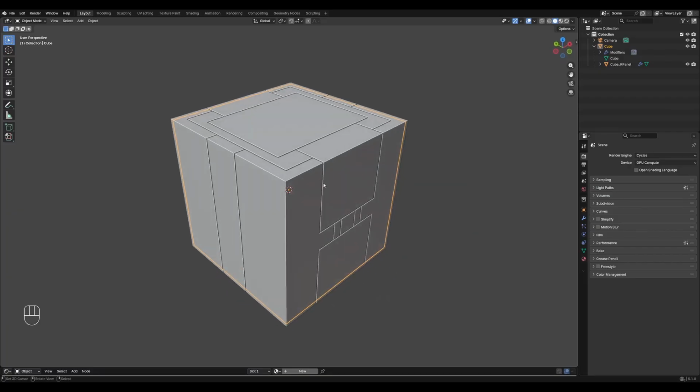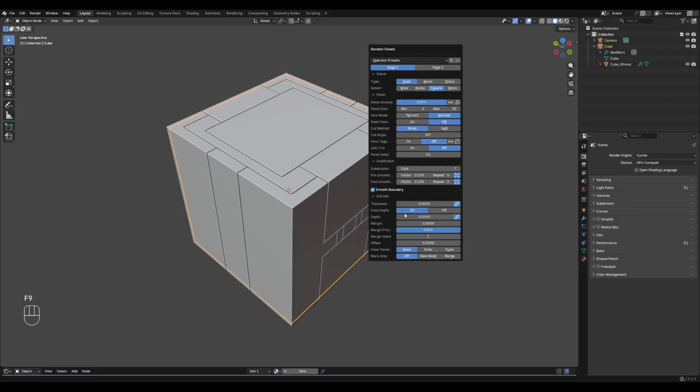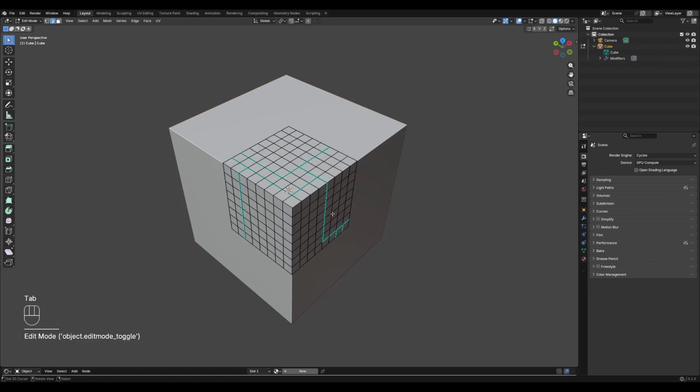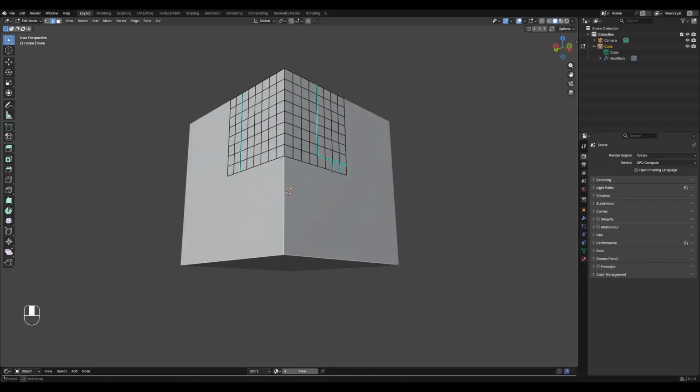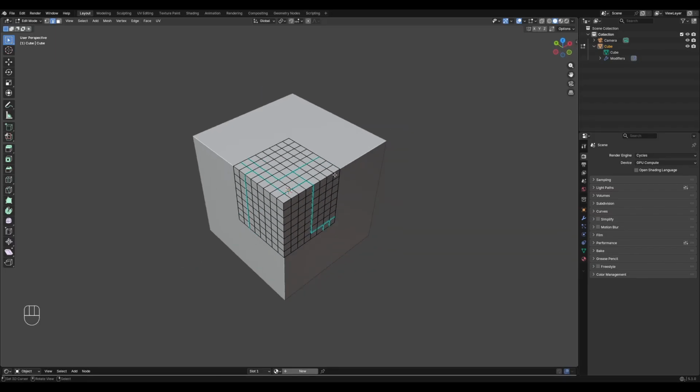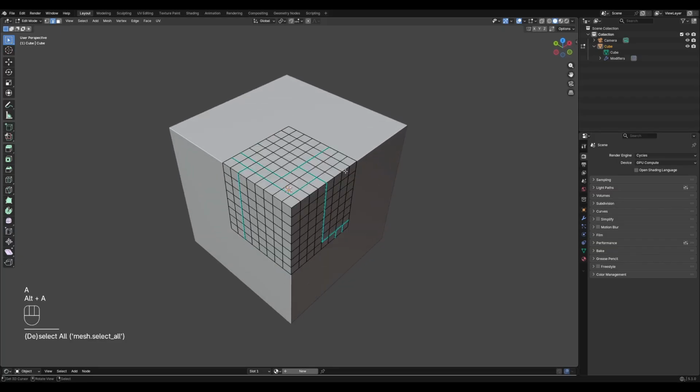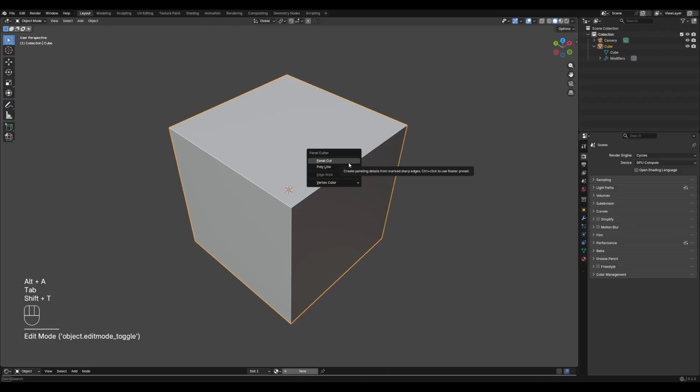This actually looks good. So let's try this one. And this time we're going to use the merge. Merge means the work mesh will be subdivided and the mark sharp edges generated there. So this is a destructive method, unlike the non-destructive option, which is the new mesh. So if we merge this to the work mesh, you can see that we have the subdivision here and also the marked sharp edges. Now we can continue using this option, for example, and then go to panel cutter.